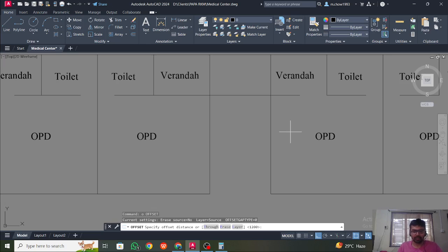So if you have a staircase of tread 250 mm, just use this. So you have one riser here in one flight. I'm counting 2, 3, 4, 5, 6, 7, 8, 9, and 10. So if you have 3 meter height, then this is enough. If you have more, then you can add more risers also.